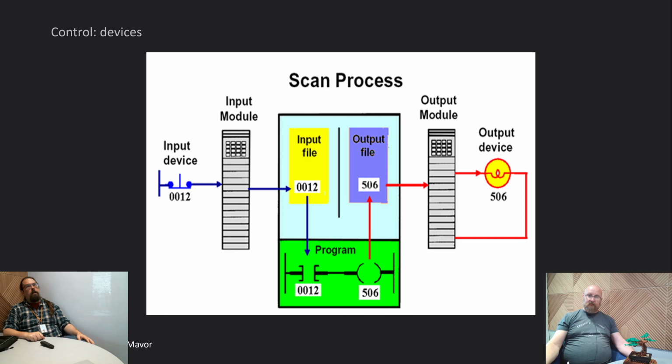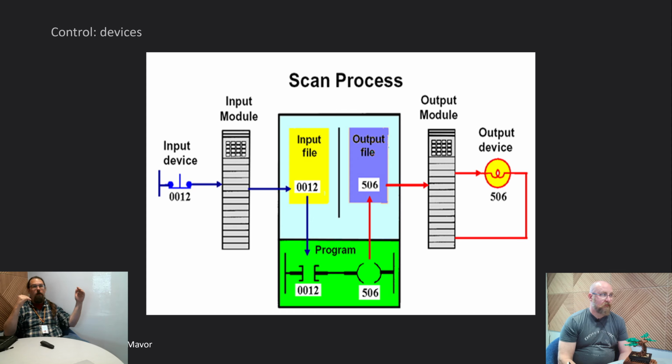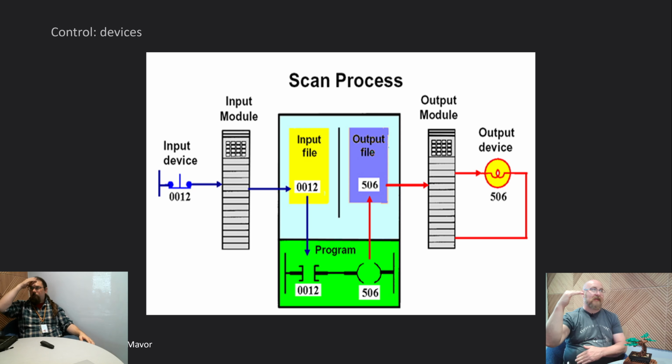This aspect of PLCs is really important to keep in mind, because the key thing you should take away is that the input signals and the output signals are wholly separate from the logic that is actually being run, and the evaluation of the logic happens all at once every scan cycle. It does not happen on an input by input basis or output by output basis, or line by line code execution either.